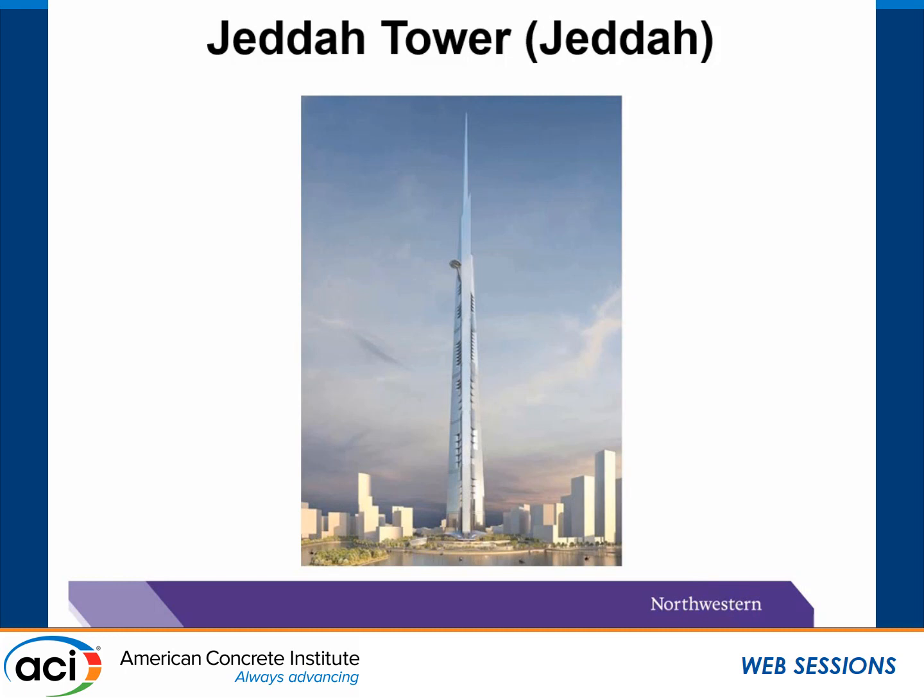However, the modulus is a critical design factor, especially for high-rise buildings. An optimum goal of Young's modulus for a high-rise building is 58 gigapascal. To reach the higher requirement of Young's modulus, the concrete has to be stronger and stronger in terms of compressive strength.